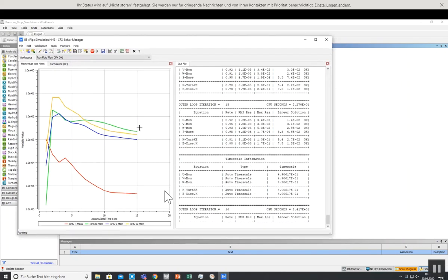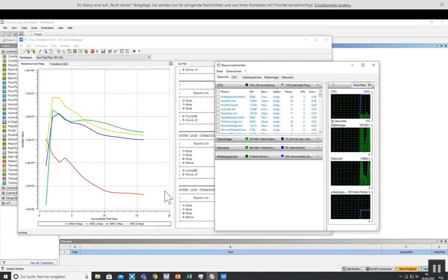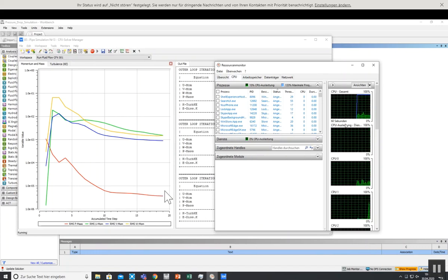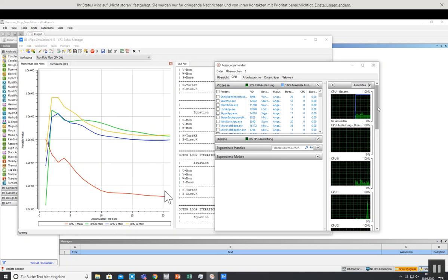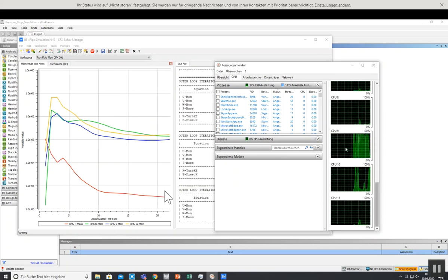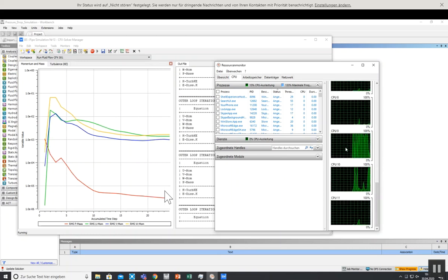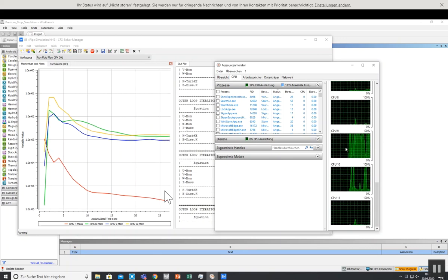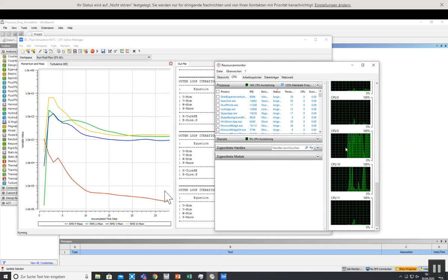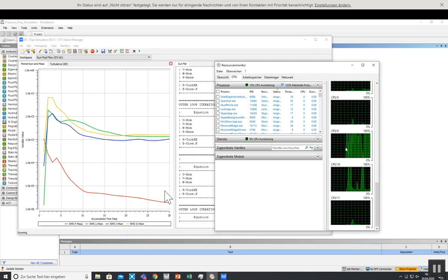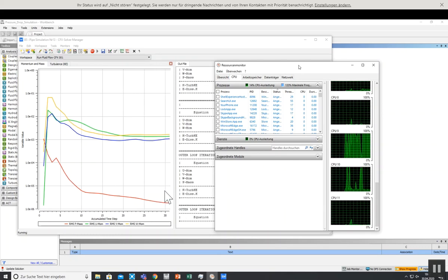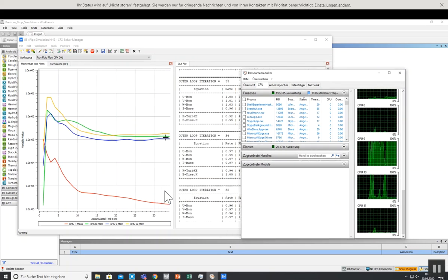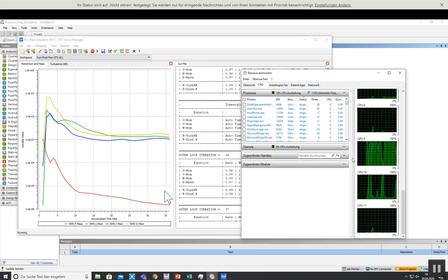Of course, a little bit slower than the other simulations, because it has many more mesh cells and it's a tetrahedral mesh. And we only use one CPU, CPU 9, but it will take, I think, about 1 minute. We can wait a bit for the 100 iterations. Convergence is still okay. It's not so low, but doesn't matter.